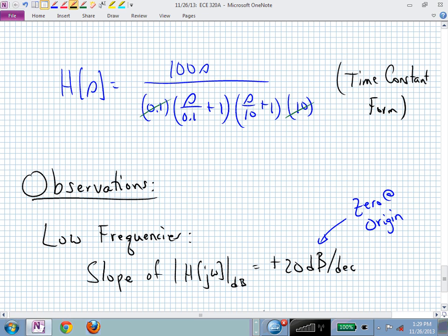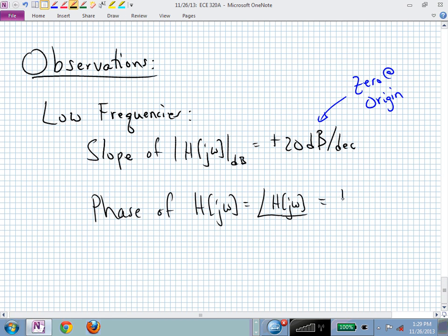And again, you might be keying in on poles and zeros at the origin. They are always active. They're always on. And you have a 0 at the origin. What's that 0 going to give you? It's upstairs. It's contributing a constant phase for all frequencies, and you told me earlier what the angle of j was. 90 degrees. And it's upstairs, so that's going to be plus 90 degrees at low frequencies.